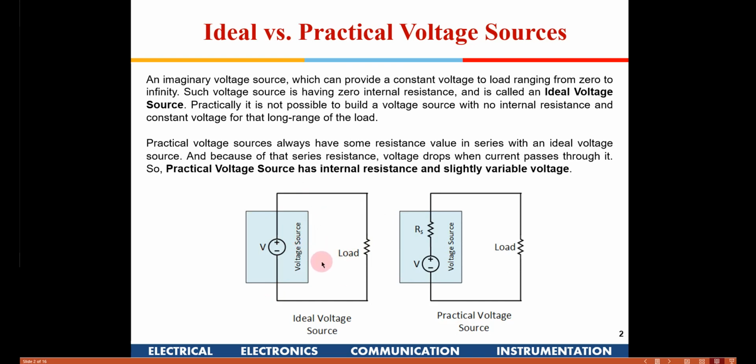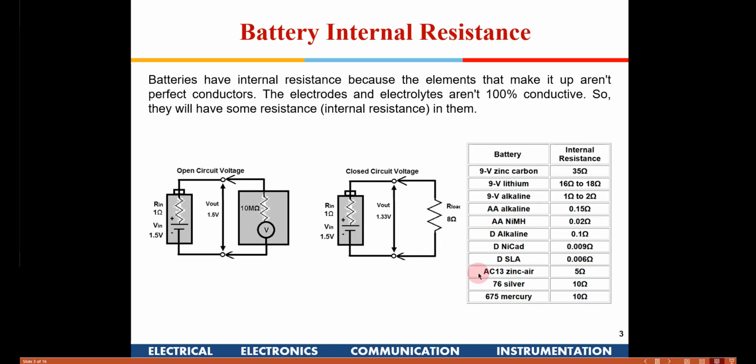So while doing calculations, you will just use V equal to IR, Ohm's law, without taking into consideration that there is a limitation on the current. Whereas when we do an actual implementation of a circuit, that may not be possible, as this source may not be able to provide that kind of current. Okay, so these are the differences between an ideal source and a practical voltage source, right?